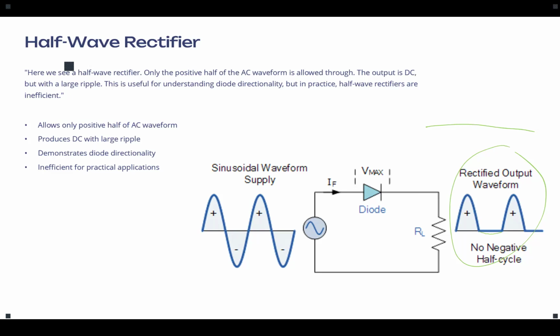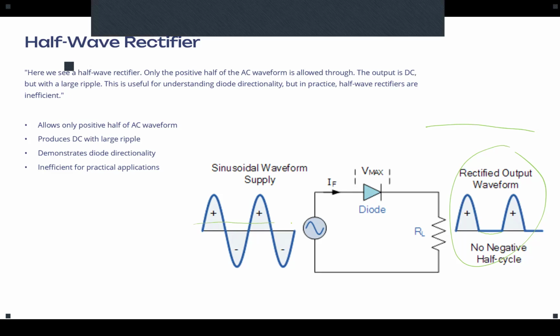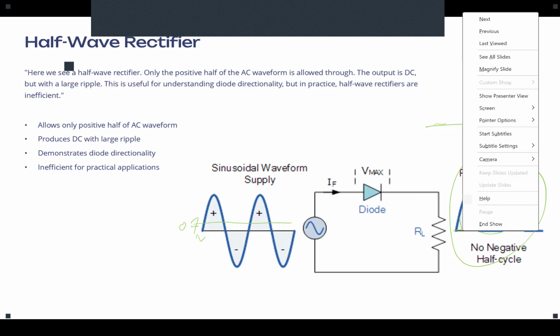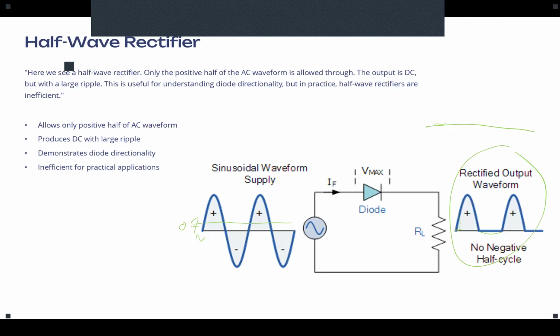Yeah, that's correct, perfect. We said the diode would not conduct until we pass that threshold voltage, the V on. Let's say this is the voltage on, like 0.7 volt for a silicon-based diode. Below that it doesn't conduct current. So in reality we have zero here, and we start conducting when the voltage exceeds 0.7.